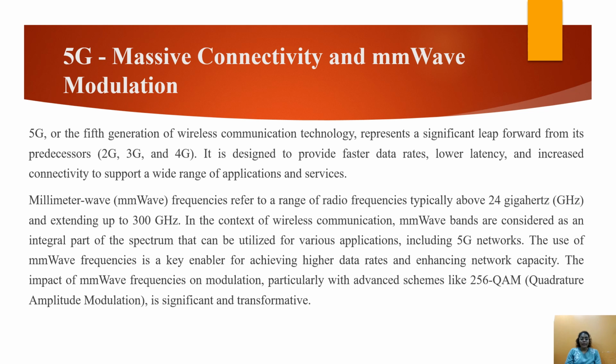Millimeter wave frequencies refer to a range of radio frequencies typically above 24 GHz and extending up to 300 GHz. In the context of wireless communication, millimeter wave bands are considered an integral part of the spectrum that can be utilized for various applications, including fifth generation networks. The use of millimeter wave frequencies is a key enabler for achieving higher data rates and enhancing network capacity. The impact of millimeter wave frequencies on modulation, particularly with advanced schemes like 256 QAM, that is quadrature amplitude modulation, is